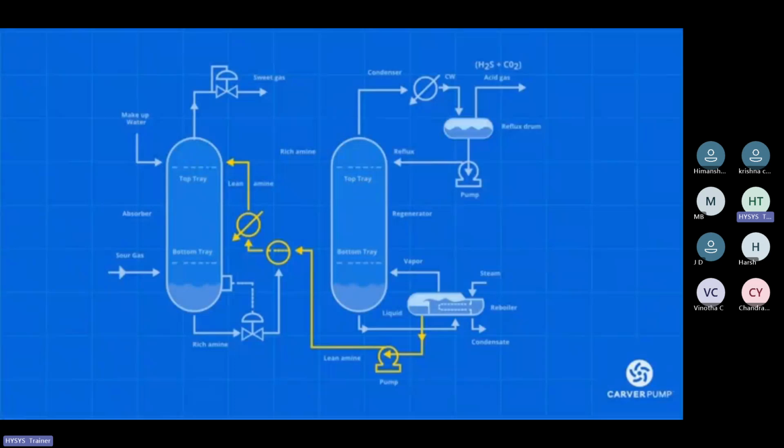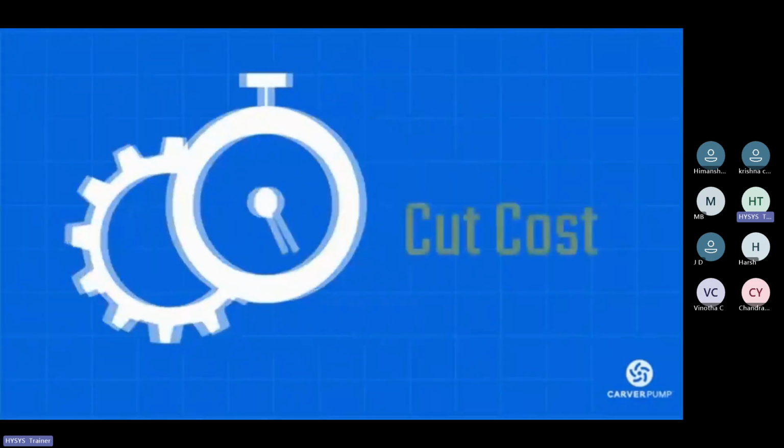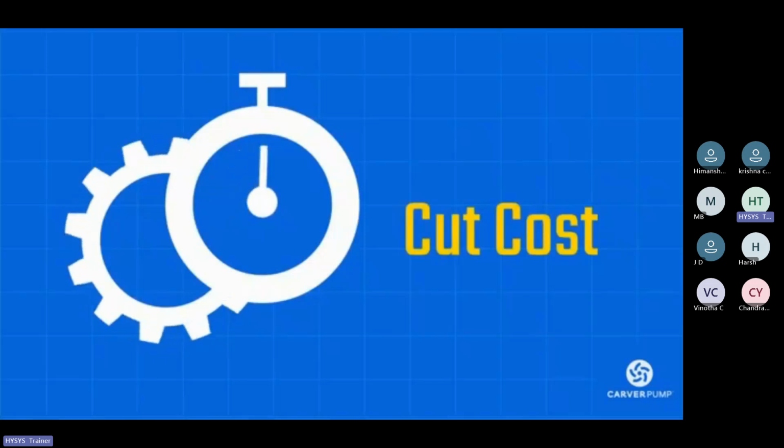The vapor from the reboiler re-enters the stripper column, rises to the top and through the condenser, and is finally discharged. A system like this is effective and efficient. It can cut costs since the amines never leave the system; they simply circulate.